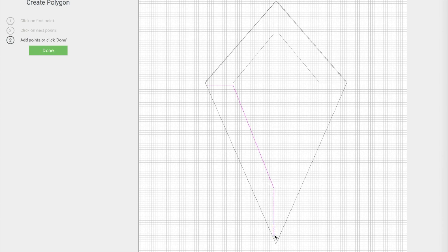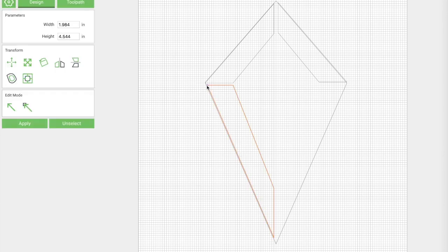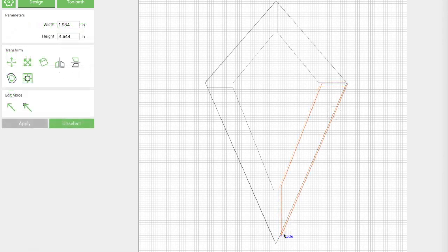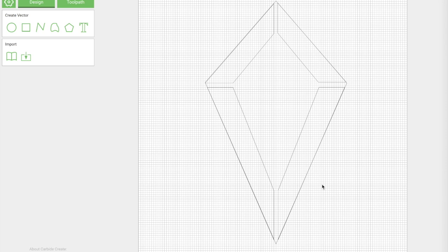Again, I'm not going to be exact, I know that. And there. There. Okay. So that's got that. And if I want those to be about 1/8 of an inch apart, that's 2 squares. So I've got that now. I'm going to copy it. I'm going to flip it and see whether or not we've got good alignment there. That's actually looking pretty good. And it's easier if you grab the node ends right here and snap them down to that grid. That's going to give you a better alignment each time. And that looks like I've got those pretty symmetrical.